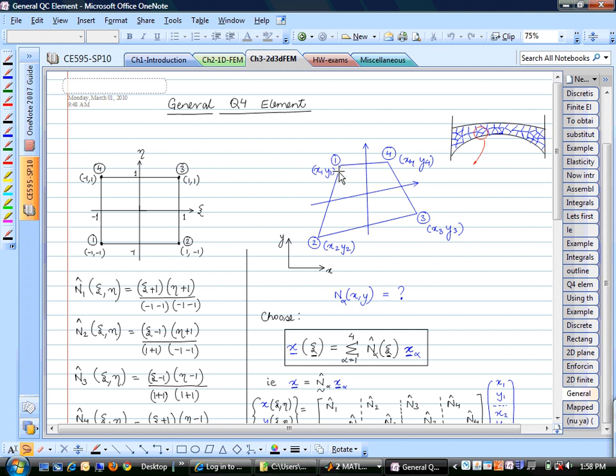So here I'm saying that for node 1, if you give me the coordinates x1 of all these 4 nodes, I need to be able to calculate all these finite element approximations, all these element matrices, and assemble them and so on.